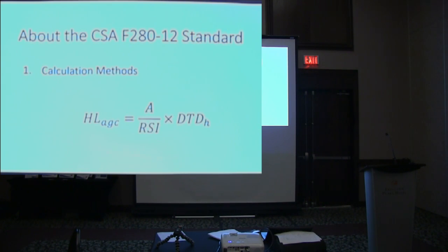They give you a whole bunch of formulas that look something like this. This is how you calculate heat loss above grade conductive through any building element, whether it's a wall or a window or whatever. You have the area of it, the thermal resistance of it, and the temperature difference across it. That's one difference you might notice from the old methods. There are no more heat loss multipliers, heat transfer multipliers, nothing like that. We're directly measuring the temperature difference across every building element and getting the heat loss through it. Simple as that. Well, no, it gets better.